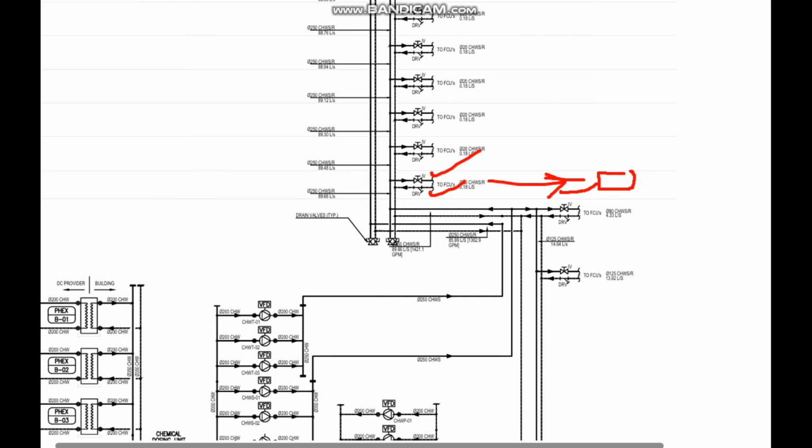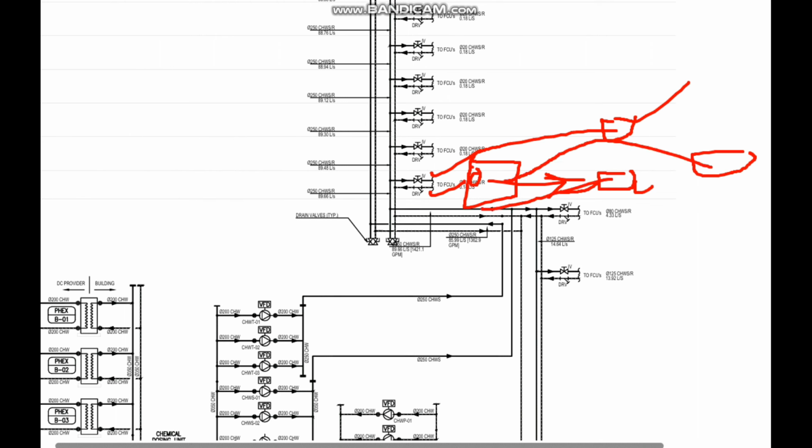So if you have multiple FCUs here, for example, this is apartment 1, this is apartment 2, this is apartment 3, we have to monitor the thermal consumed energy through a BTU meter. First, this connection will go to one BTU meter room. From the BTU meter room there will be multiple meters. For example, the apartment 1 meter, the apartment 2 meter, and the apartment 3 meter will be there. So there will be 3 meters in this BTU meter room. From there the supply will go to each apartment, so we can monitor the consumption.